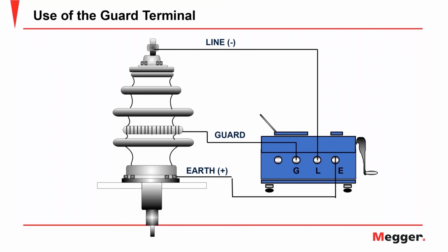That would mislead the operator to think possibly the bushing is bad. It may have been hit by lightning. There could be a crack in there, and the crack doesn't have to be visible to the naked eye. Minuscule amounts of distance provide a path for current to flow. It doesn't have to be visible, and yet it can defeat the purpose of that bushing.